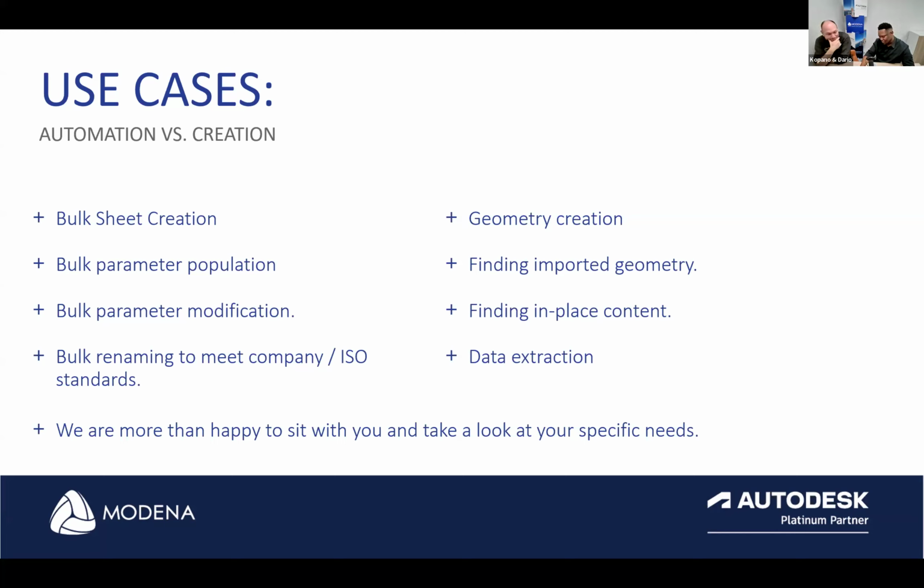So maybe just to add to that question, I think it's very much important to also keep the template at a modular or lean size. Absolutely. Yeah, we have seen some where the templates are actually 200 to 500 megs. And that's without even putting in a duct or a light. Oh, yeah, no. That's not easy to update or upgrade to your new Revit as well. A lot of people don't actually know this, but Autodesk's recommended maximum Revit file size is 160 megs. And you're starting off with a 200 meg template. 200 meg, it's not going to work. You're already over the limit. So yeah, it's definitely something to think about.